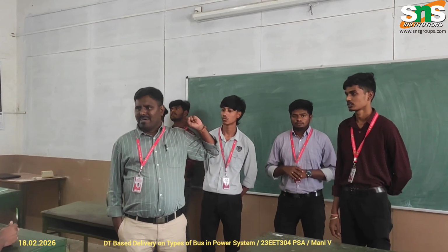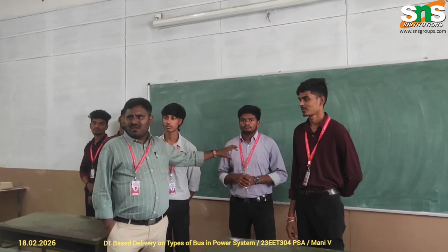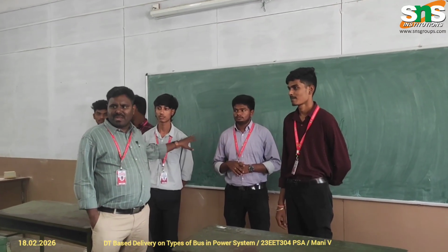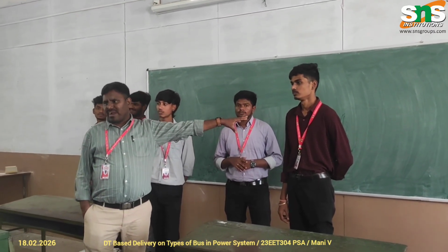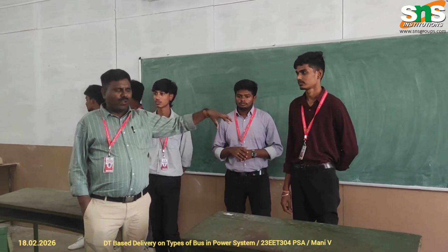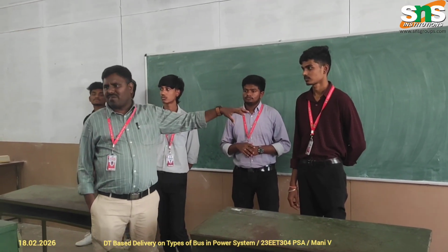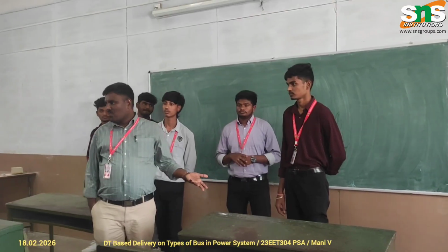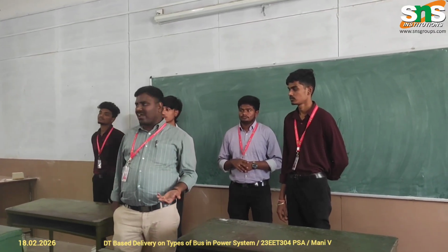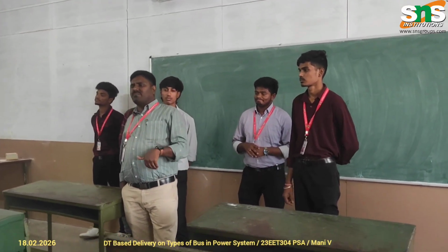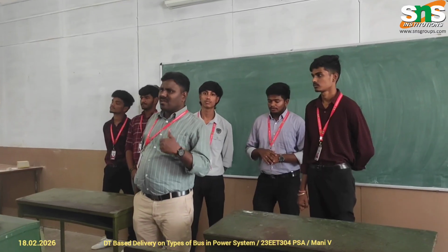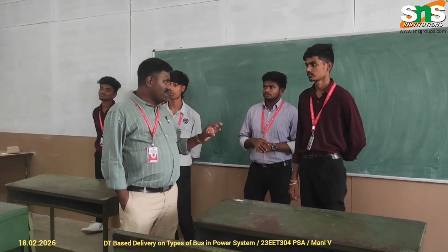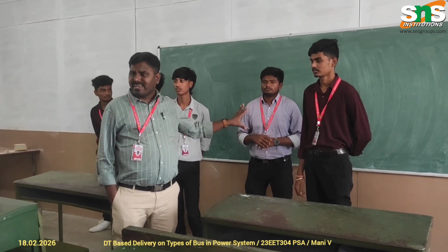So you can draw electricity from the bus. It is denoted as a PQ bus because you know the value of P and Q, where P is the real power and Q is the reactive power. Based on the known values of real power and reactive power, it is called a PQ bus. But here we don't know the bus voltage and the phase angle of the voltage. So we have to determine both the voltage as well as the phase angle of voltage. That is nothing but a load bus, or a PQ bus.